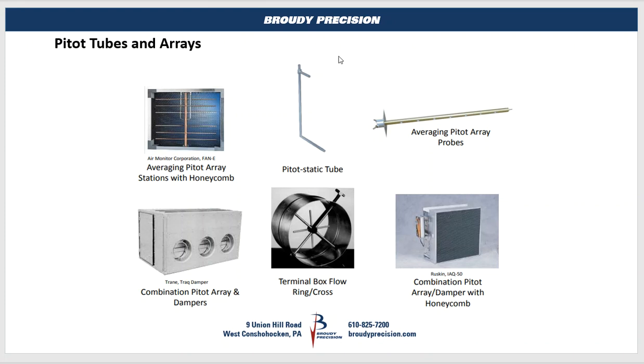All of these technologies, these pickup tubes and arrays that you see on this screen, are for the direct measurement that is usually seen inside of ductwork, straight pieces of ductwork that are measuring an airstream of some sort, whether that's outside air or supply air, downstream of the motor or upstream of the motor, but these are inserted into ductwork typically.